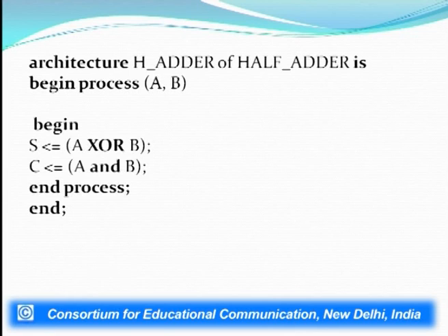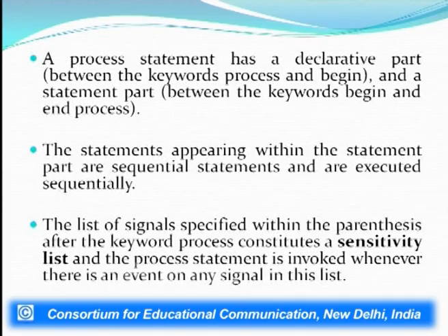Then since we have begun a process, we end a process, and since we have begun an architecture, we end the architecture also. Here it is not mandatory to give the name of the architecture, only end semicolon also suffices. Alternatively, we can also mention end H_adder, which will mean the end of the architecture.